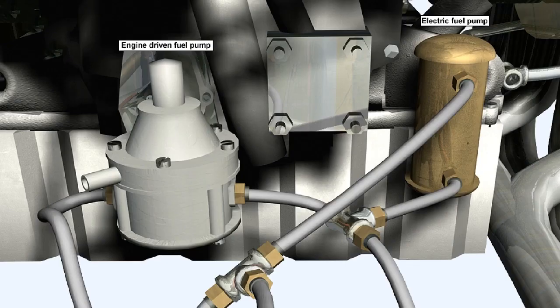The system is normally equipped with two fuel pumps, an engine-driven one and an electrically operated one, which are arranged in parallel. Because of the parallel pump arrangement, when the engine-driven pump is not operating, fuel under positive pressure from the electrical pump can flow independent of the engine-driven pump. This allows the electrical pump to be used in case of a malfunction of the engine-driven pump and for engine priming and starting.